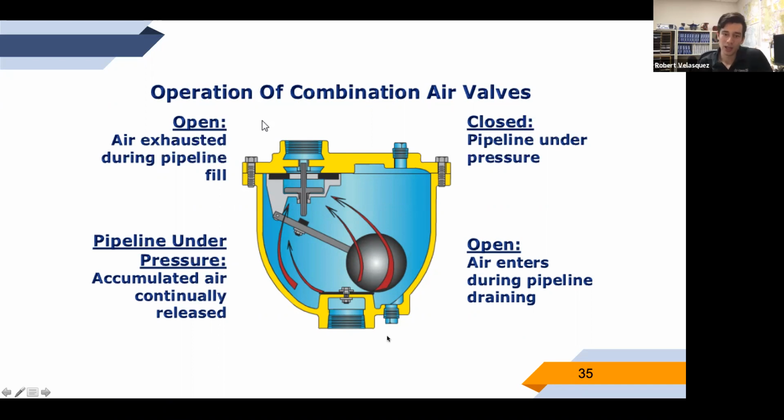And so, as I was saying, this metal stem and check here, this is the air vacuum portion of it. And when you start up the system, air will leave out. And then as water comes up, it'll push this ball up and it'll pressurize and it'll close that.